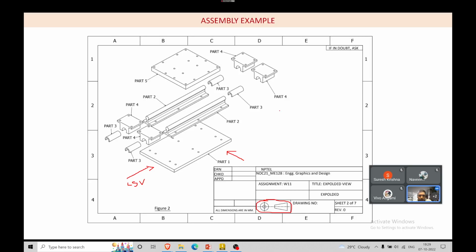Now I'm going to create 2 concentric circles. Radius 3.75 into 2 means dia 7.5. Is it 7.5? Yes. Dia, so this into 2, dia 5. So dia 5 and dia 7.5, 2 circles I am going to create. Circle 7.5. Again one more circle, 5. So now we created the 2 circles. Now let us create one line from this to here.